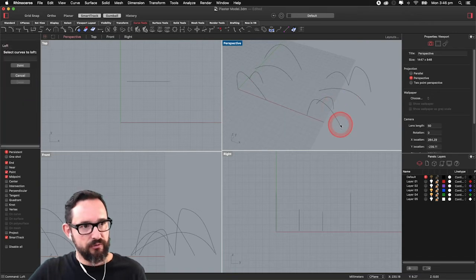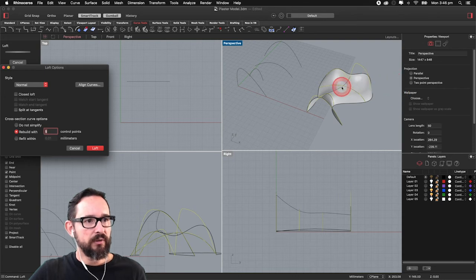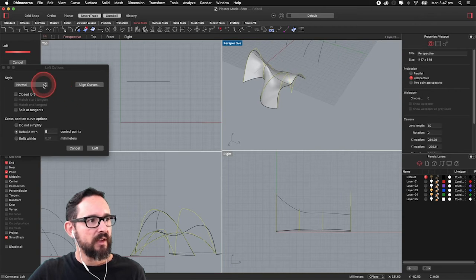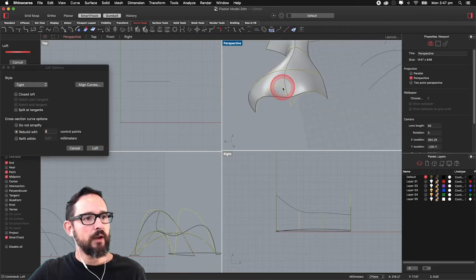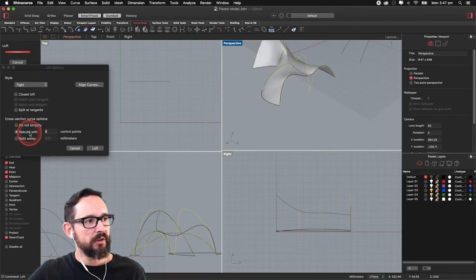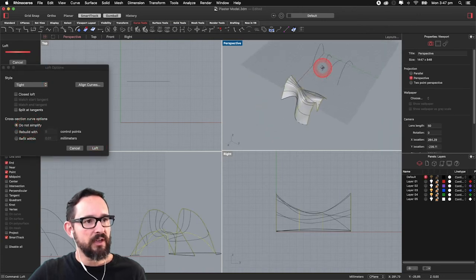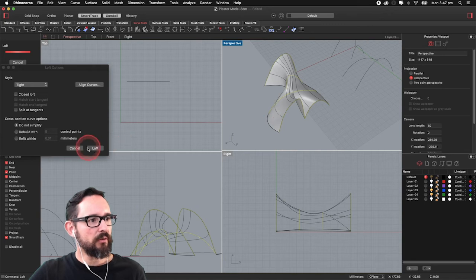So again, always choose the loft from the same side. You can drag and see, but if there's a twist, you already know what's happening. So in this case, you see the kink doesn't have a total reflection because it averages it. Let's make it tight. And yeah, it doesn't allow you a lot because I'm rebuilding with 5 points. Actually, I do not want to simplify. And if I don't simplify, you see, all the lines are still straight, the ISO curves, and it allows you to have an accurate outcome. Okay, so I'm happy with that.